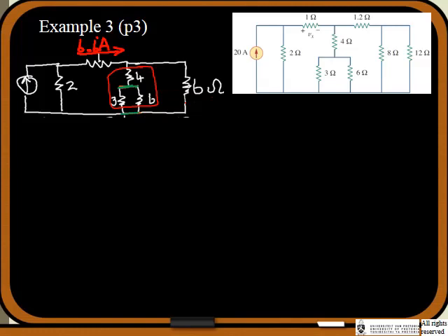We also saw that we could combine this parallel combination, which is already encircled in red, as a 6 ohms. But where's the part that we're looking for? Where are we in the big picture? If we go back to the original circuit, what do we know now? We know that the current flowing through there is 6.6 amps. We found out that the parallel combination of these three resistors was 6 ohms, which is the ones over there.